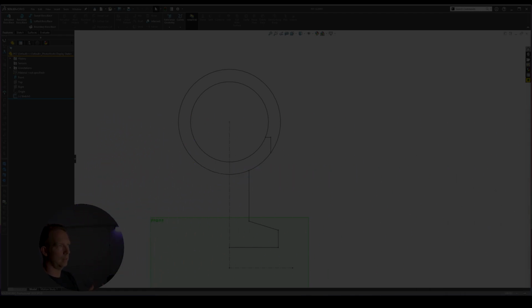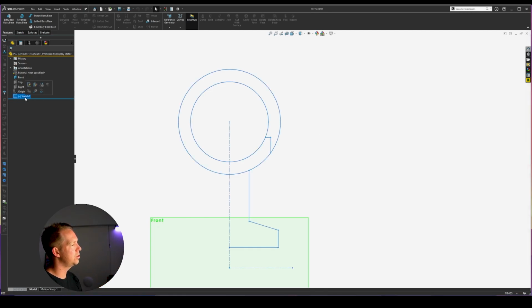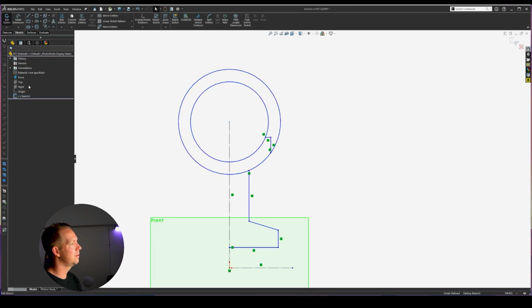Okay, we're back. Now, we've saved our file, we've saved our sketch. How do we get back to editing our sketch? Again, multiple ways of doing things. The first way, you select the sketch in your feature tree, and you click this icon here, which says Edit Sketch. That's going to take you back into Edit Sketch mode. You can tell you're in Edit Sketch mode because you can see those two icons in the top right, including the red cross. And in the top left, you can see the Exit Sketch button is depressed.